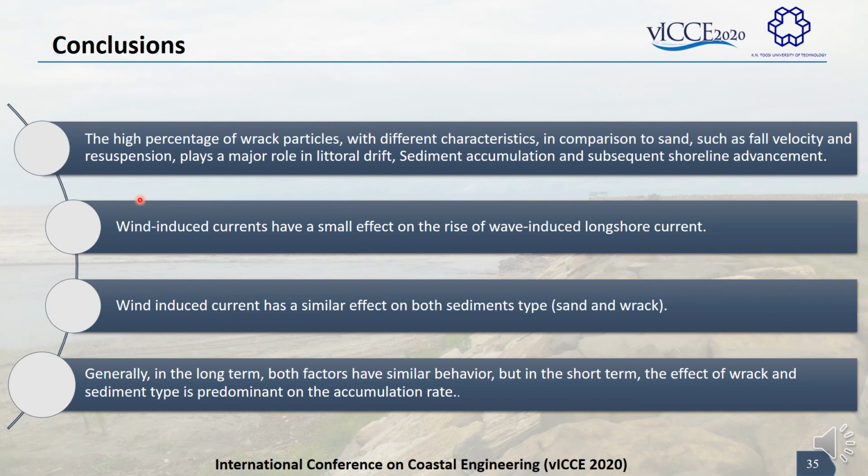Okay, the conclusion is described here. We can see the high percentage of wrack particles with different characteristics in comparison to sand, such as fall velocity and resuspension, play a major role in littoral drift, sediment accumulation, and subsequent shoreline advancement.